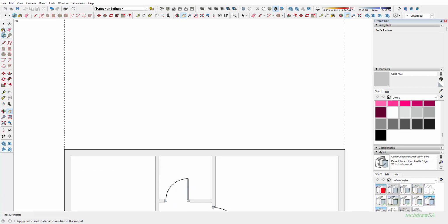What I'm going to do is pretend for this demonstration purpose that our foundation's lowest end is going to be about there. Obviously you can still draw in the roof overhang here on the floor plan itself as a hidden detail line, but I'm not going to draw that in now. So I'm going to now start with the foundation. Remember, this projection line that goes up here is for the external wall. So that is not the start of your foundation. Your foundation you still need to work out, and its default is 600 by 200.